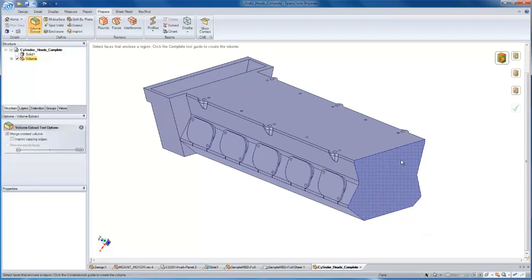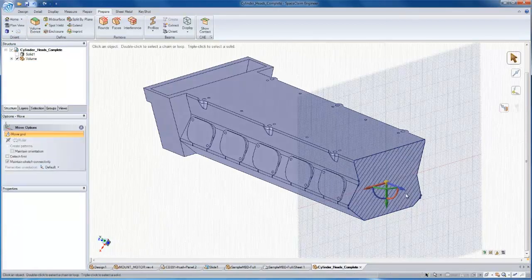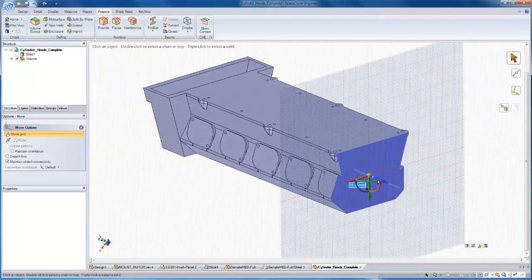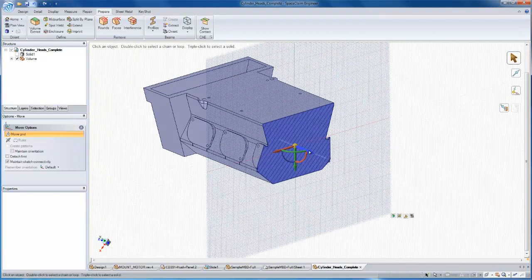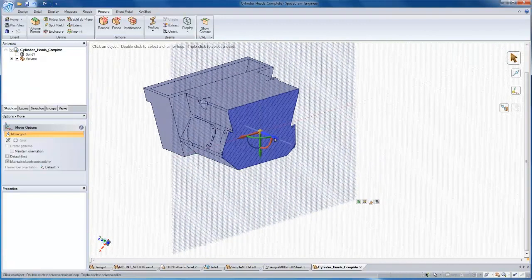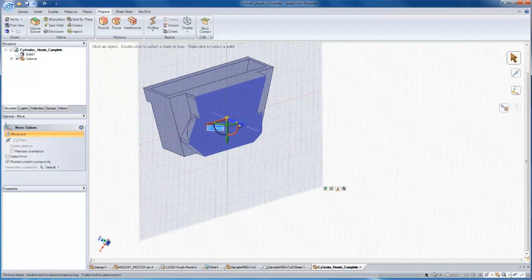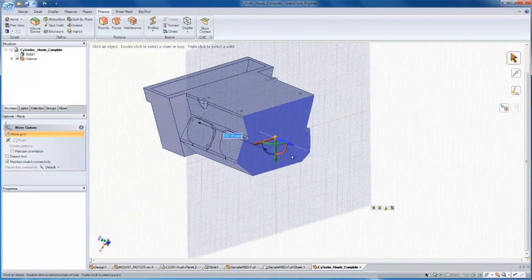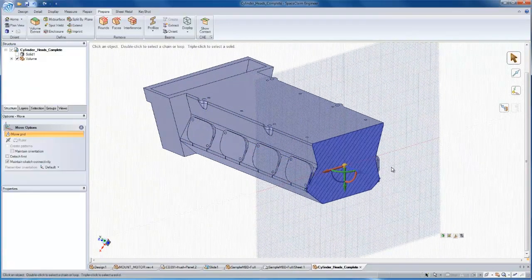So if you are a supplier of CATIA models to someone and you want to hide internal sections, internal features that are proprietary, but you need to show the outside of something, well, this is an excellent tool to just get that job done lightning fast. Literally, it took 2 seconds to create this after I selected the surfaces, the capping faces and edges. And look what you have. In my cross section, I've got a solid body everywhere, so you know that you've hidden everything on the inside, and it's not just a shell of something on the outside.